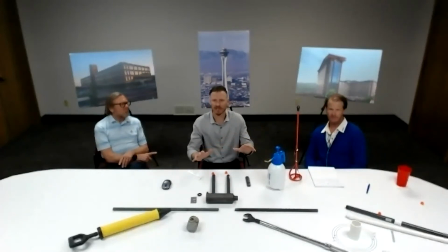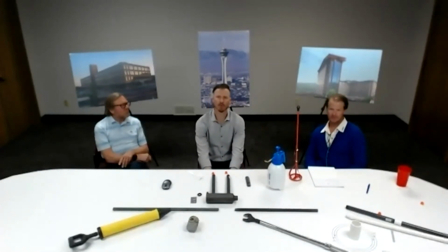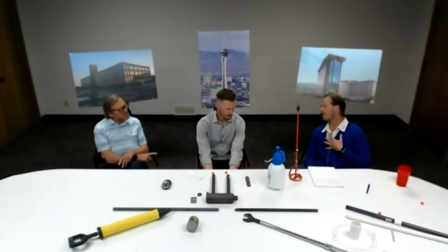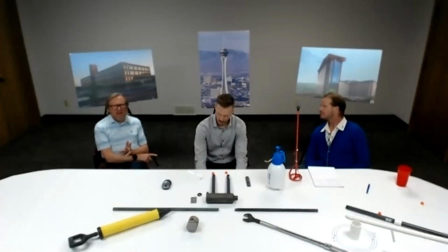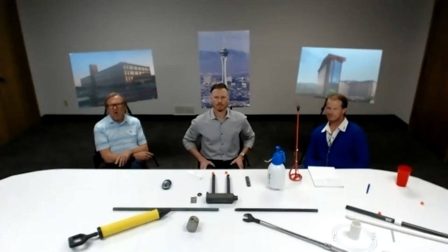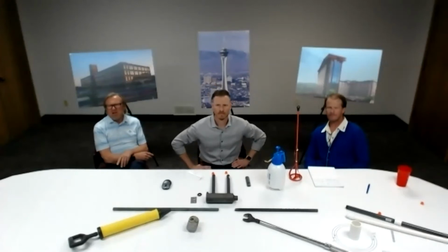So it's no different than you would find on your typical pour strips on how they're designed. And typically on the cantilevers in the middle, our designs usually include enough PT to hold the cantilever piece, when we're the EOR. Other cases would be, you could always put a small 2-foot piece of form in and put reshoring in right away to strip the forms. There's a lot of options there.